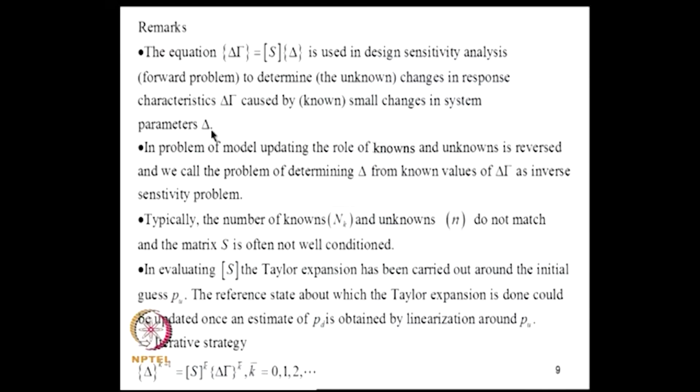Here we determine the unknown changes in response characteristics, delta gamma, caused by known small changes in the system parameters. Now, in the problem on hand, the situation is quite the opposite. Here in the problem of model updating, the roles of knowns and unknowns are reversed, and we call the problem of determining delta from known values of delta gamma the inverse sensitivity problem. The word inverse sensitivity is associated with this description.